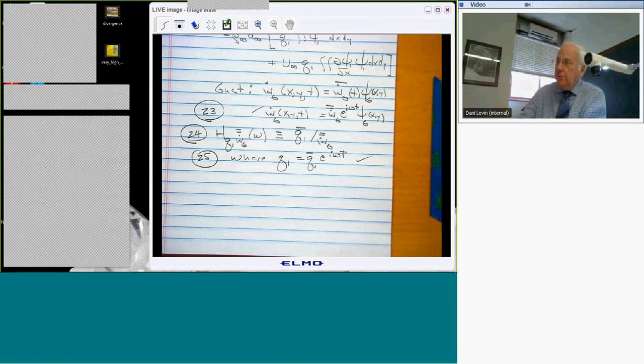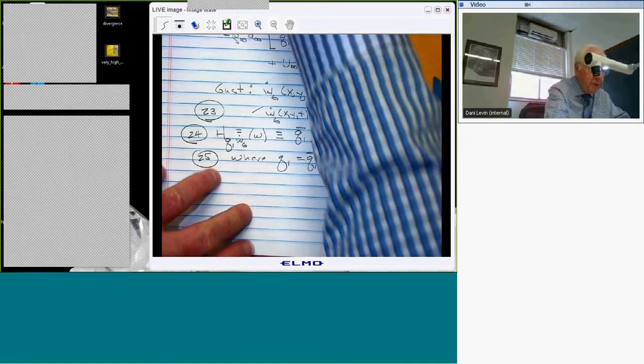Because for a linear system, that's the only thing that can happen. For a nonlinear system, you can have harmonics, you can have superharmonics twice, 3 times, subharmonics 1/2, 1/3. You could even get chaos. God knows what could happen in nonlinear systems. But for a linear system, this is the only thing that can happen. So it's the same, really. But I think of it as the gust frequency which imposes that frequency on the structure after the transient dies out. Okay? Good question.